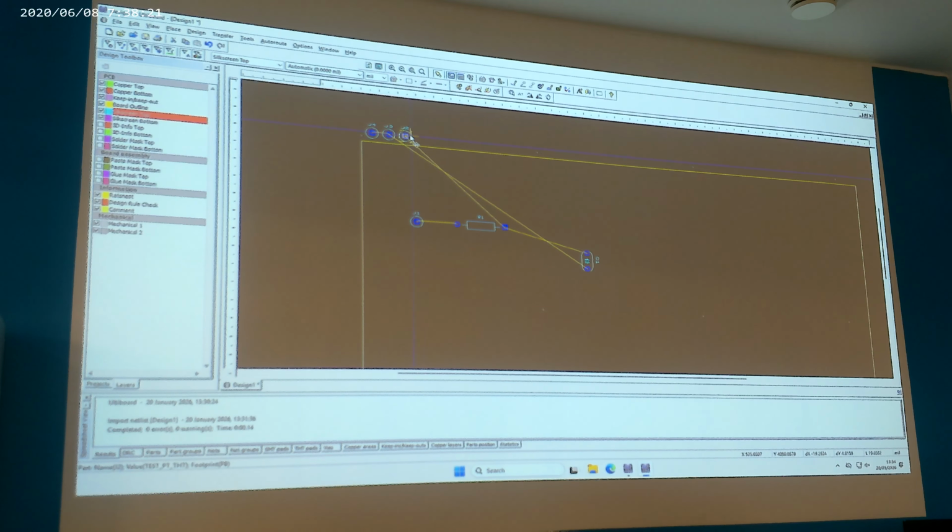Okay, next thing I'm going to do is take one of the other pins and bring that pin here. Well, from the drawing, I know that that's that pin, I know I've got the capacitor here, but I want that capacitor to go down to ground. So let's drag in those other two pins. Get hold of it. I can't get hold of it, sometimes you can't. Come on. I've got it. So that's one of the grounds, and that's the other ground. And you can see you've got that nice blue line that helps you align things a bit.